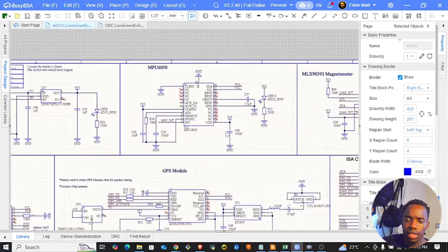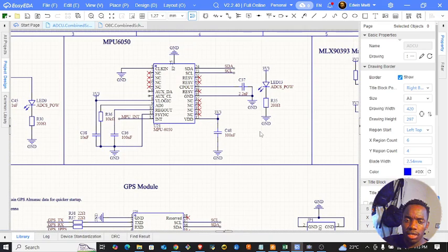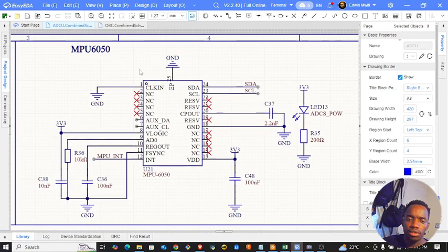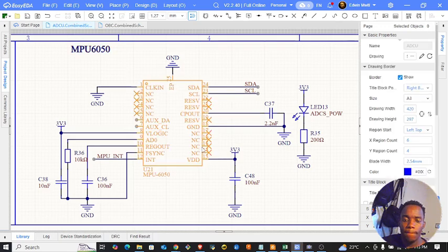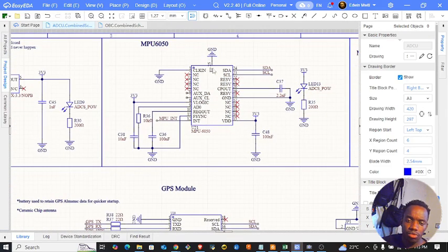Right, so the other thing for determining attitude is, how do we get the accelerations? The best chip to use for that is the MPU 6050, a very simple basic chip, and it gives us all the data that we need. The MPU 6050 will give us the XYZ accelerations plus the gyroscope values, which means the angular velocity of the CubeSat in space. And the data rate is pretty high, which is cool.